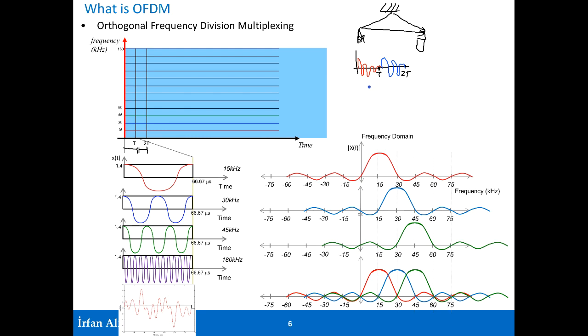And then when you send these over and the mobile receives these signals with a particular delay, let this be tau 1. So here you have a delay from the time that it's sent to tau 1, and you essentially have between 0 to t the first symbol, and between t to 2t the second symbol. And the first symbol essentially has this OFDM thing that you had sent in 0 to t, and the next one is delayed over here.